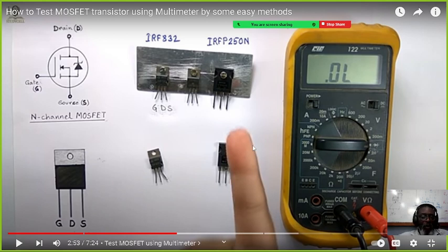You understand? It's really a voltage coming out of the lead. As long as you are testing resistors and diodes, remember, to test a diode, it has to be reverse biased or forward biased, doesn't it? Current has to go through it. So where does the current come from? The current comes from the meter.